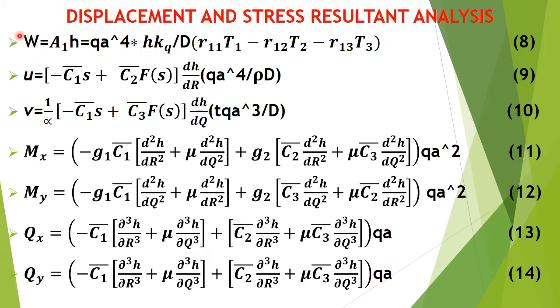And then we derive our expressions, and we got the expression for the in-plane displacement along the x-axis, which is u. We got that of the y-axis, which is v. We got our values for the moment along the x-axis, the value of moment along the y-axis, and shear force Qx along the x-axis, and Qy, which is shear force along the y-axis.